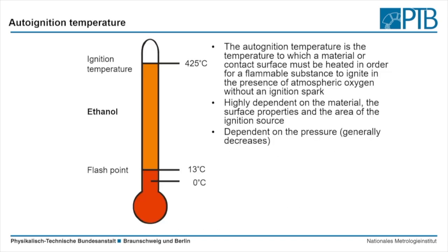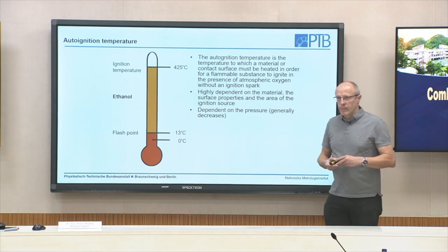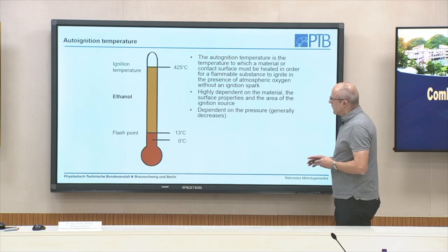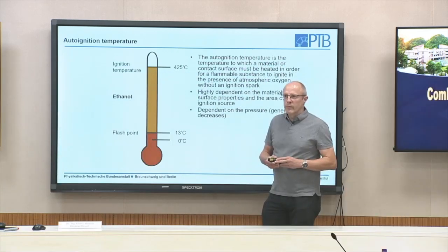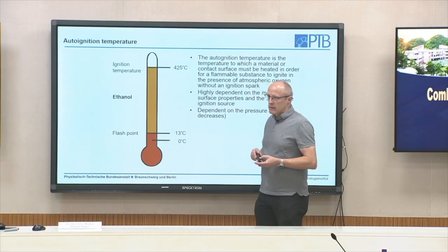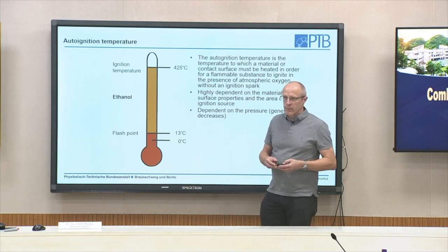So, auto-ignition temperature. As we have seen with hydrogen, when we looked at this PT diagram concerning the ignition limits, there's always a criterion at which temperature in a closed vessel we can ignite our mixture without an additional heat source.